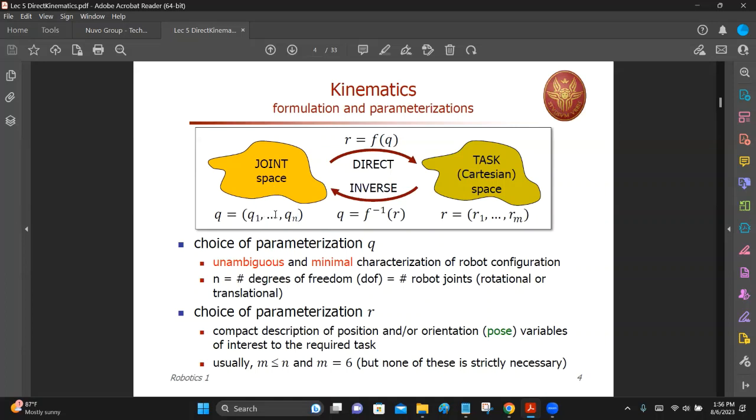So this recording of joint angles is good for industry, for most of the industrial applications. This accuracy is okay, but if you are really serious about the accuracy, you should not do it that way, right? You need to have a very accurate model of the manipulator. And then once you have this F, you can put your R in and calculate Q mathematically, not just by reading the encoder. Okay, so there you can see how serious research is done and how a not very serious industrial application is developed. So this is the difference between the two.